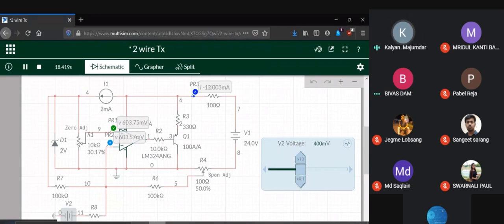You can try this out for 25% and 75%. Normally it's tried at 5 points: 0%, 20%, 40%, 60%, 80%, 100%. That is normally done to prove linearity. But anyway, at the 50% point we saw that it is linear.